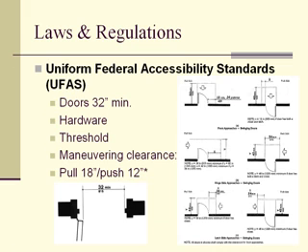Another requirement for the doors is what is called a maneuvering clearance. So we are all on the same page with the maneuvering clearance, think of this as you approach a door. When you approach a door, if you are going to open that door, let's call this the pull side, it means you are holding that knob and pulling it towards you.